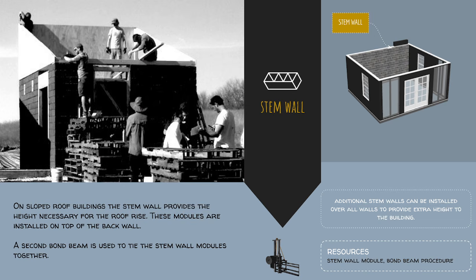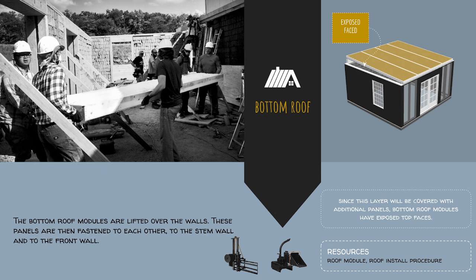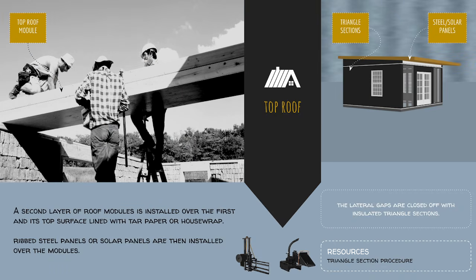Stem walls, in the same construction method, you can have sloped roofs very easily by raising one side over another. We tend to gravitate to flatter roofs so we can put PV right on top of that. We make roof modules. The roof modules that we installed on a hangar are quite big. These are human size. Basically, we built ones that were 3 by 16 feet as roof modules. You can do that. Right now we're going to the trusses that we're building, and then in this specific case we're lifting up the whole roof assembly with a telehandler using some mechanical assist. So yeah, top roof sections like this.